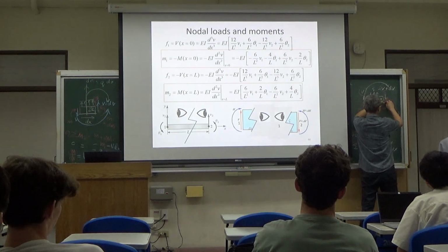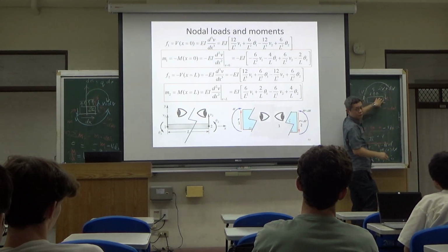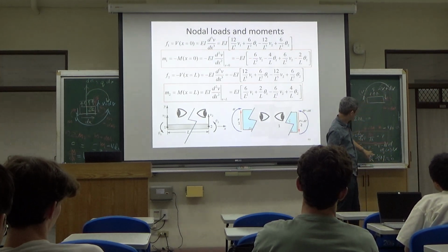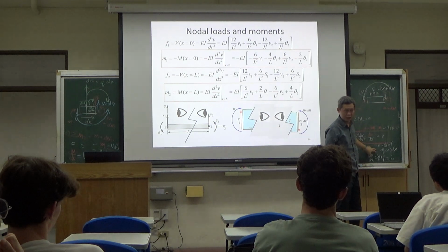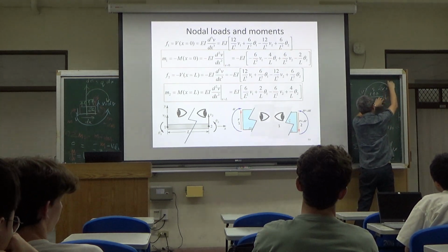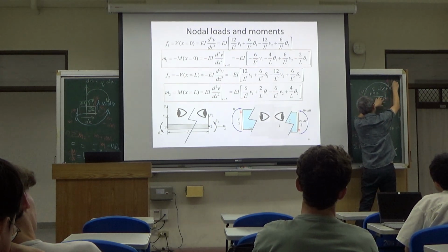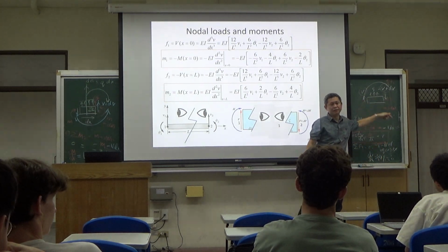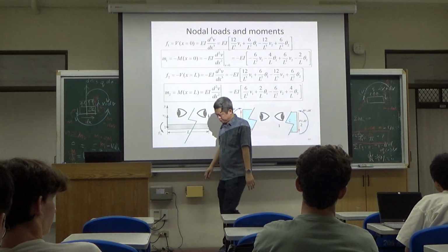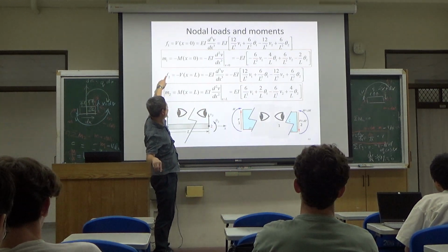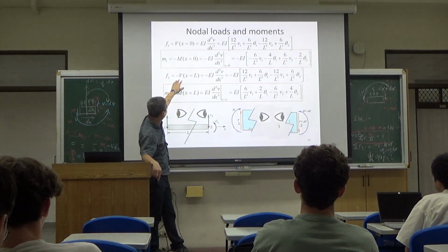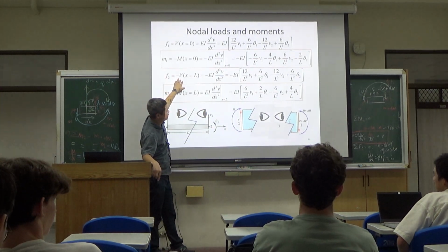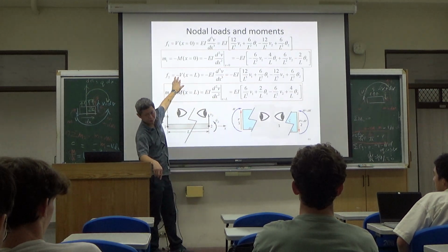The shear force here is downward to fulfill the condition. But I define my vertical force to be F2. So isn't it that it should be minus? Your F2 is upward, which is opposite to your free body force diagram.